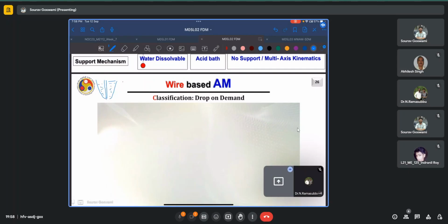Based on the need, the plunger will move, have an oscillatory motion about the XY direction, about the Z direction, and deposit small bits of material in one layer, then move on to the next by this rapid back and forth motion of the plunger. As we can see, inherently this process is more vulnerable to both intra-layer defects, defects in the same layer, as well as interlayer effects, that is the defects between two successively deposited layers. However, this is still an up and coming technology. Not many processes using drop on demand techniques exist.